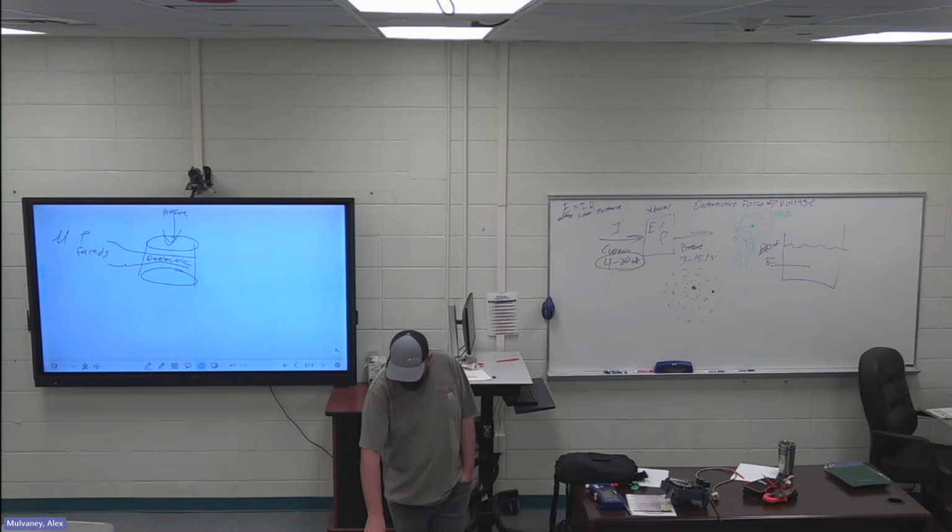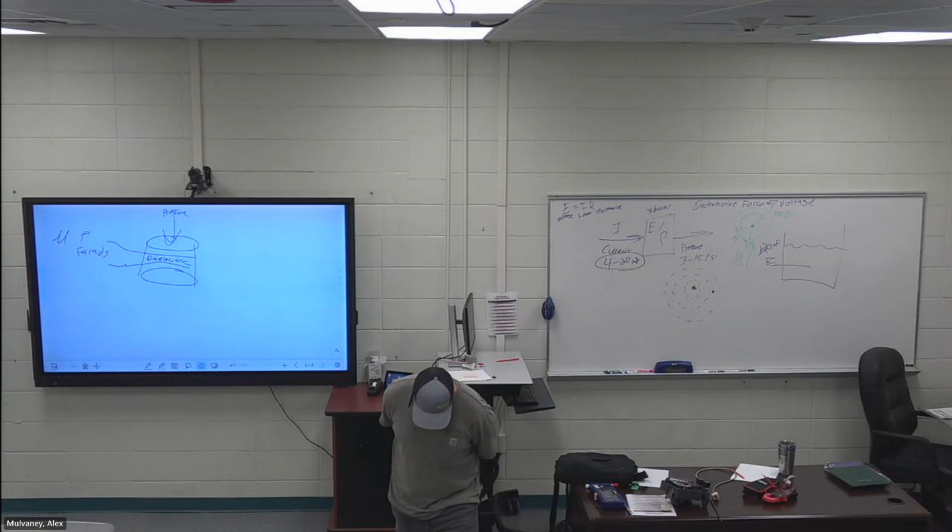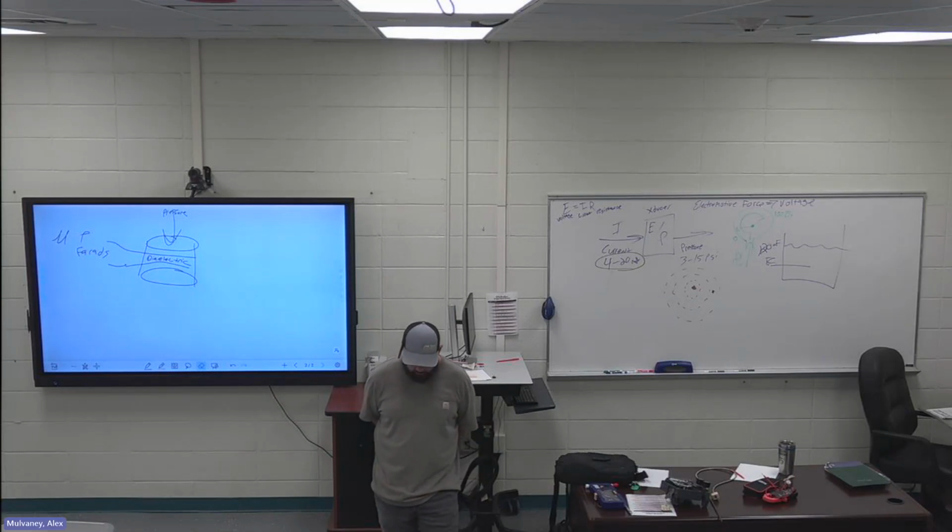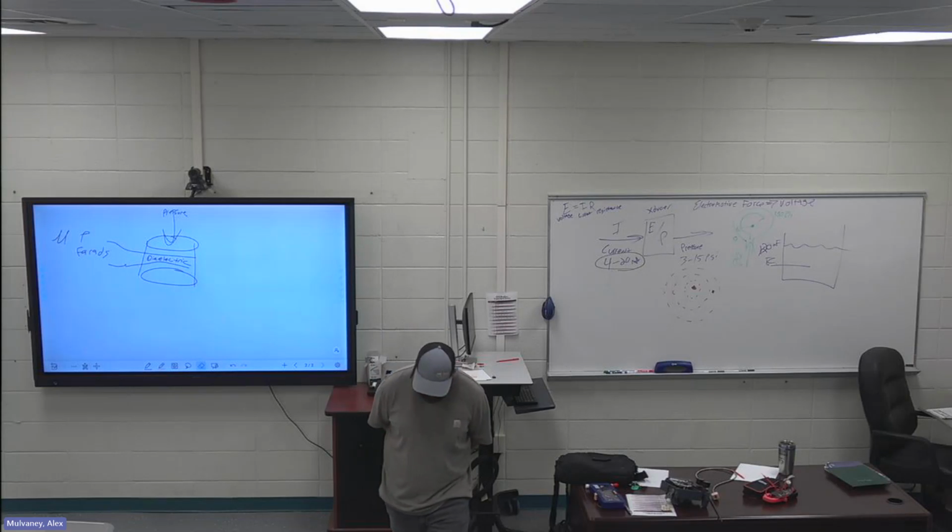Flipping over to page 24. I'm going to give you these highlights and then I'll talk about them. Got two highlights from 24 and 25. Second paragraph, right above the did you know? First two sentences are highlighted. A bare metal probe is used to measure the level of non-conductive liquid. The probe serves as one plate of the capacitor, while the tank walls serve as the other.